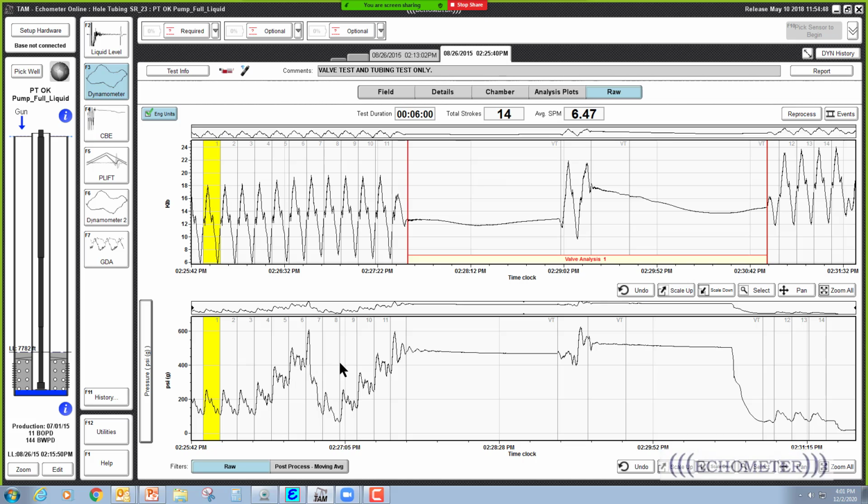because I'll have my pressure up to about 500 psi. And then when he stopped, it held pressure, didn't leak off. He did another stroke just in the middle. I think that was to check his check valve, and this really probably wasn't a valve test. And then the pressure held, and then he released the pressure.